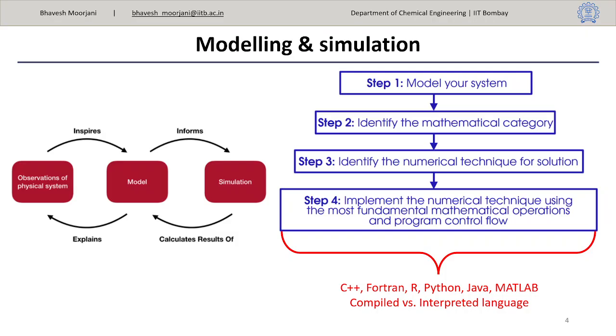In that case, let's say I vary the output temperature of my process stream. Instead of 70 degrees centigrade I want to go to 80 degrees centigrade, while the steam remains at the same condition. What will be the change in the area? I can compute that easily through hand calculations with the help of my calculator. If the process requires the temperature to be 65 degrees centigrade instead of 70, what will be the change in my heat exchanger area? Or let's say my heat exchanger area remains the same, then what will be the output temperature of steam? That sort of thing we can compute.